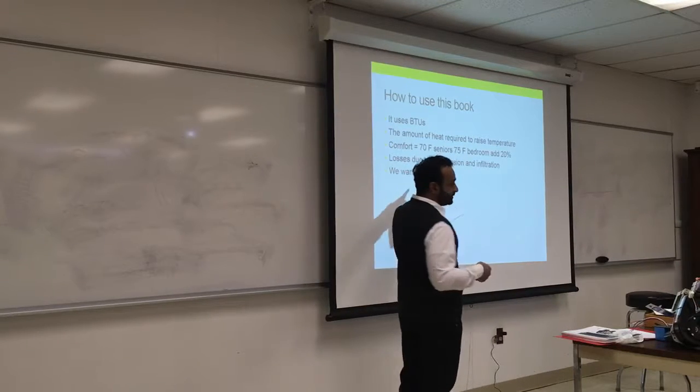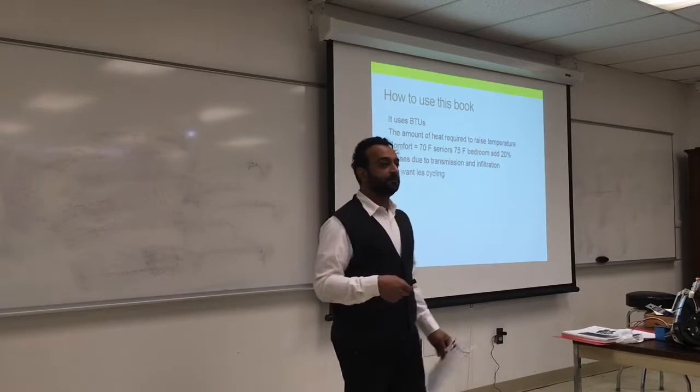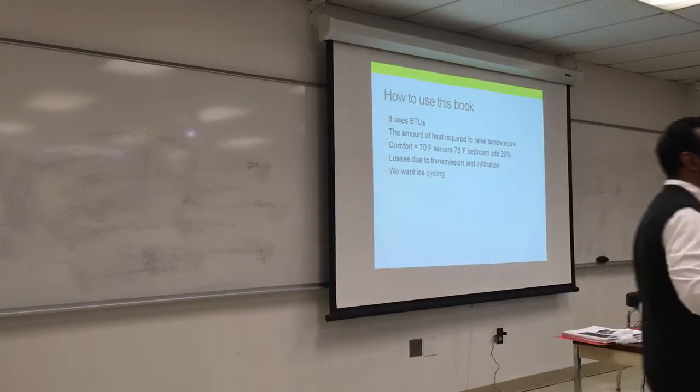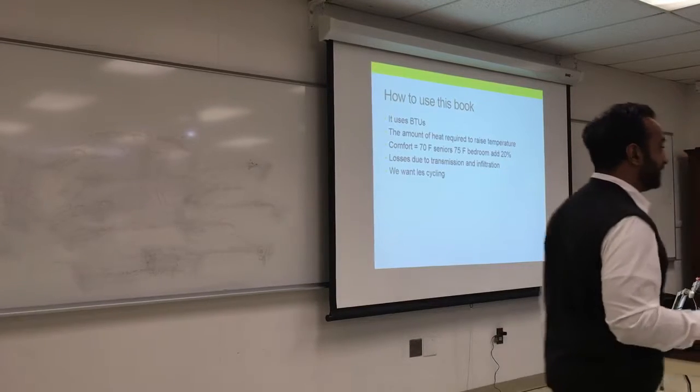We want less cycling. Less cycle, what does that mean? On and off. You don't want on and off. You want it to be steady. You want the furnace to be steady. You want your AC to be steady. Cycling causes a lot of discomfort and also wastes energy.